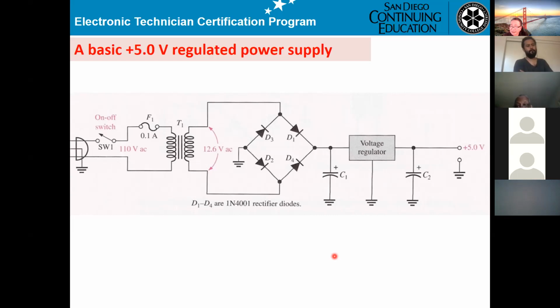That will be guaranteed. Make sure when you get the big voltage here, they don't have too much noise or high current. They short it to ground. Kill that. Just kill the noise on this input here. Right. So it basically reduces the noise there, and then afterward, C2 will take out even more noise, which might be generated by the voltage regulator.